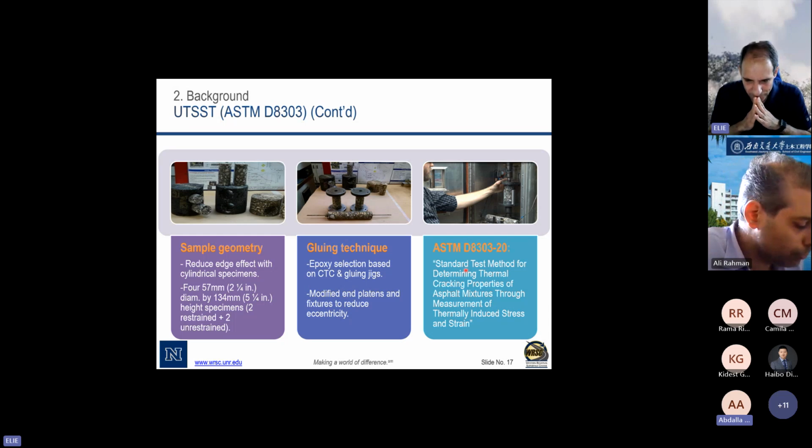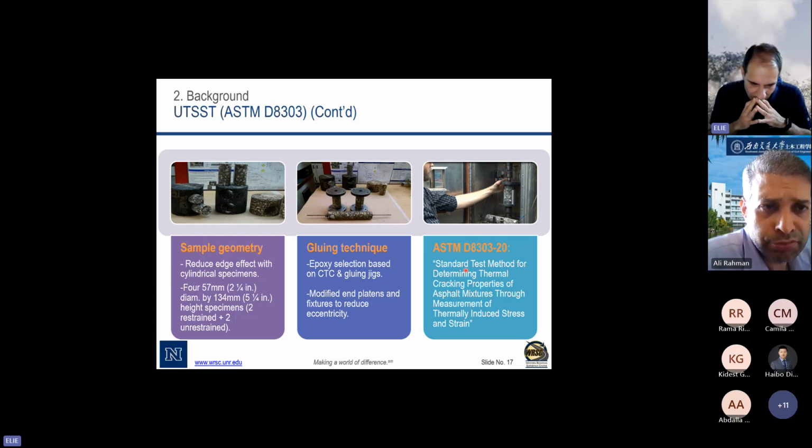The software needs threshold inputs: rutting, fatigue cracking, top-down, and thermal crack. The thermal crack failed in the first 2 years, but the rutting stays for 10 years, 20 years. I need some suggestion to solve this structurally.